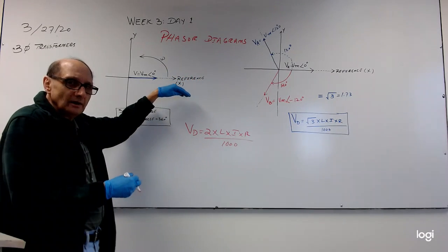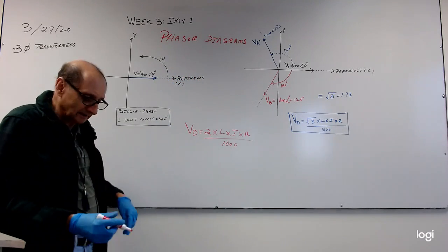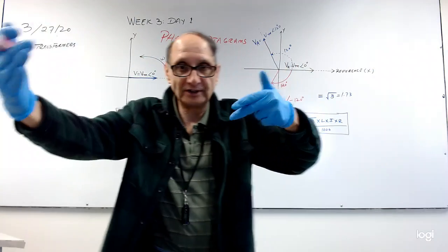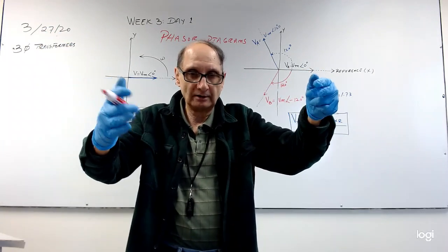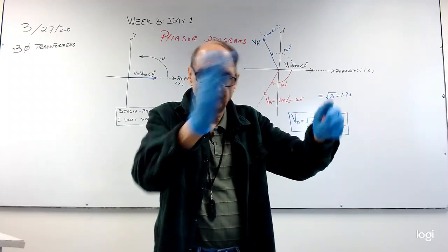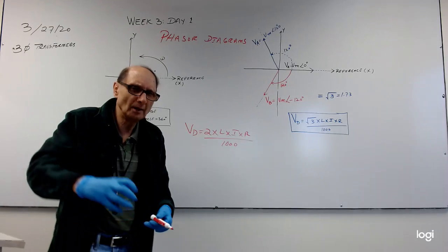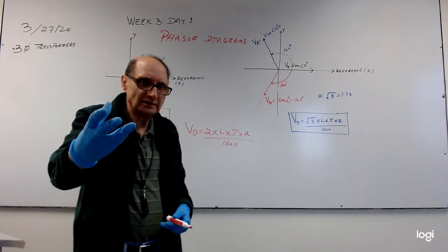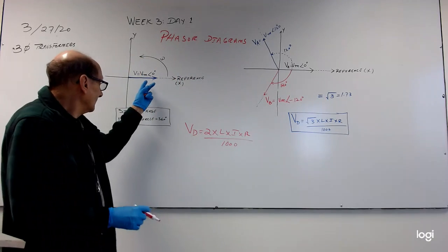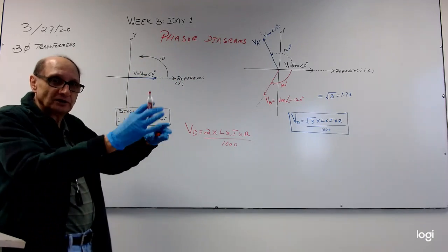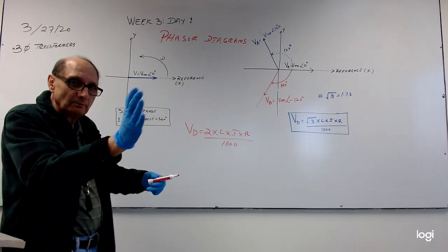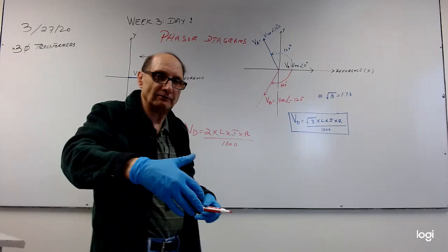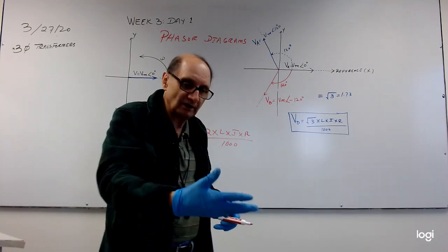Of course, if you remember inductors and capacitors from AC/DC class, if you compare voltage with current across an inductor or capacitor, there is going to be a phase shift between those two. But I'm generally speaking about voltage levels. In this case there is no phase shift between phases across a single phase, whether it's two-wire single phase or three-wire single phase.